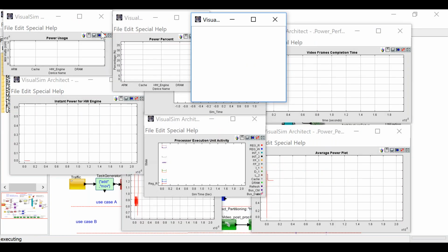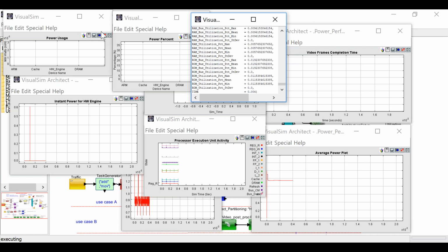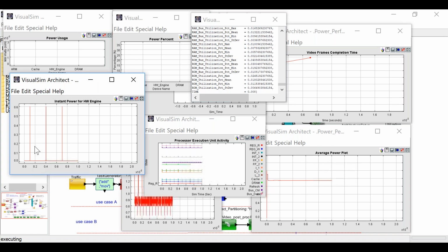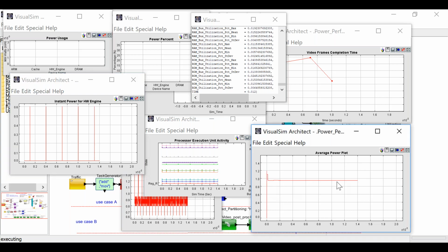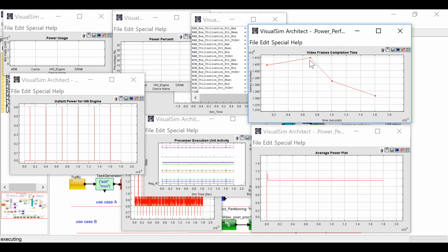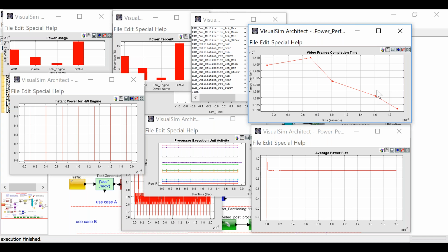So if you notice, I'm making incremental changes and seeing how the system behaves as a result of being in these incremental states. A couple of things you notice. One thing is, as soon as it finishes the task, it immediately drops to an idle state, which is almost 0. Power is looking pretty good. It's below the 1 watt of power. And the performance actually drops off a little bit, but not significantly. That's because I haven't set a transition time for the particular design.